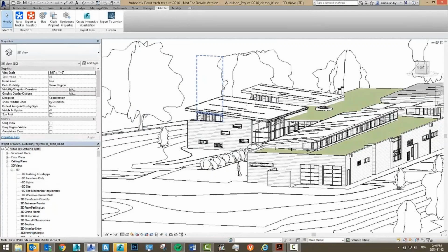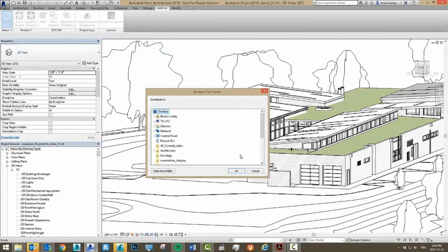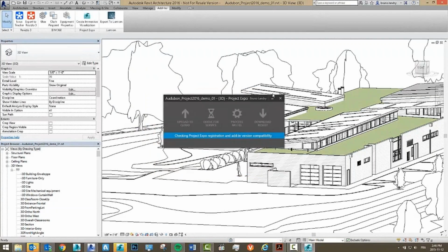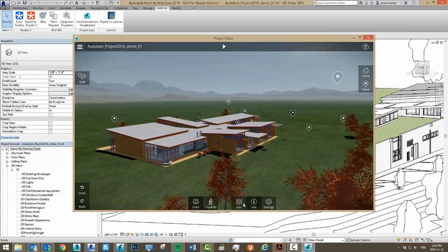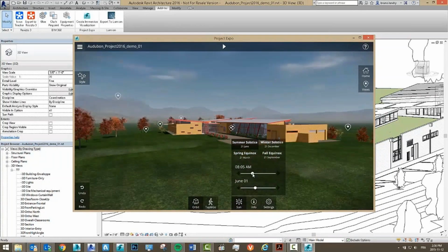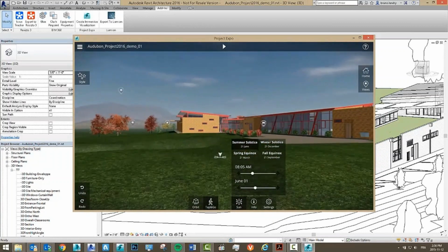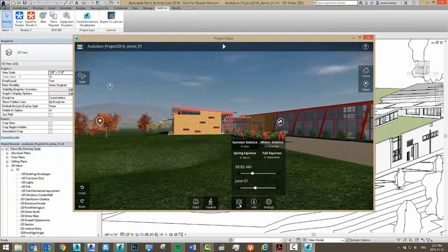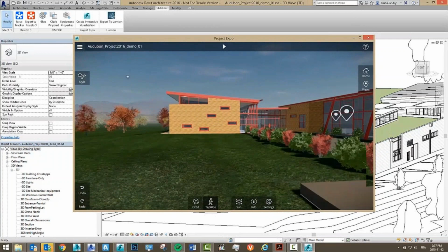And here, again, I will show a short video of how we can bring information from Revit to what we call Live. And this is really a question of several clicks. Basically we can upload the model to cloud services, and based on your bandwidth and your internet speed, you will get, within a couple of minutes, this model visualized, and you can pass through it, or walk through your model.